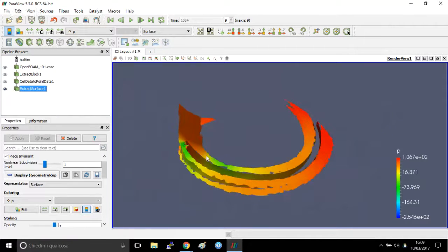Now that we performed these operations, we are ready to calculate the normals of the cells' elements. These are fundamental because the force applied from the fluid to the solid walls is made up of two different components. One is the pressure component, which is pressure times the area, and the second part is the wall shear stress.